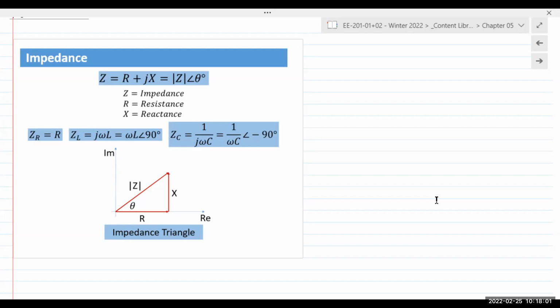For both inductors and capacitors, what does it mean when you change the value? You're talking about an AC signal. If you change it slowly or quickly, that change is measured in terms of frequency. The faster you change, the more the opposition from the inductor.